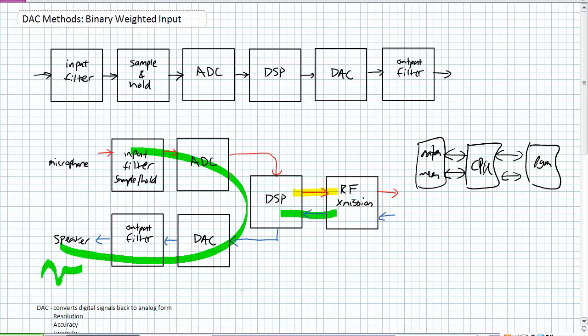One brief note before we go on to specifics of a digital to analog converter is there are other methods of analog to digital conversion. And in the cell phone example I used here, they don't typically use some of the previous methods I talked about. Most normally they use this thing known as delta modulation. Sometimes it's called a sigma delta analog to digital conversion. It's kind of like successive approximation, but totally more complicated.